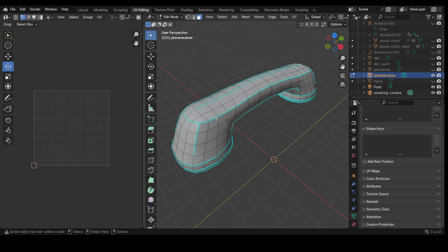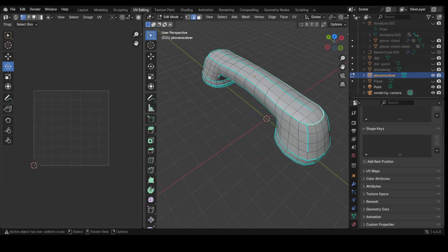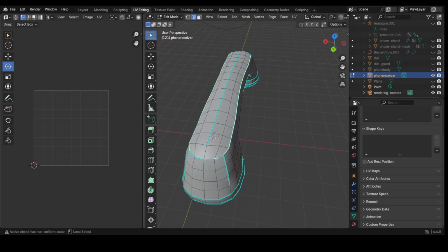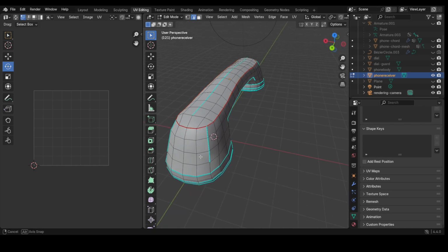into flat surfaces. So I'm going to start out first of all by going to the number 2. Alt will give me my edge loop, Alt Shift. Again, because we started this as a box, Alt Shift. This one as well, Alt Shift. And right click and then mark the seam just so that we don't lose track.